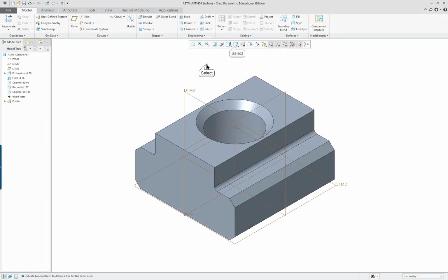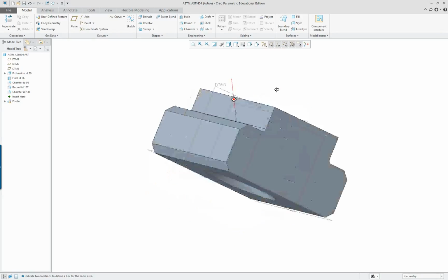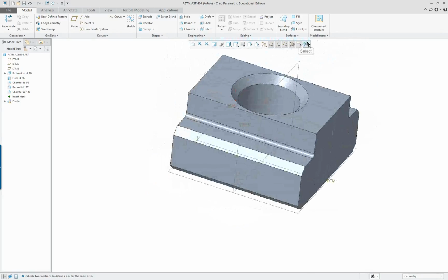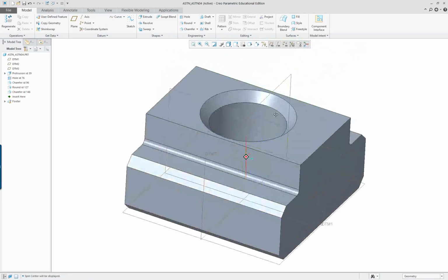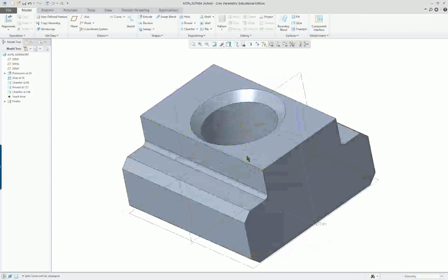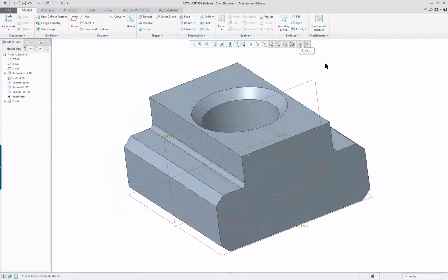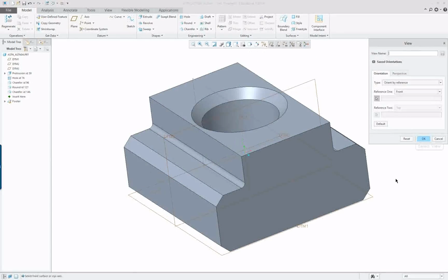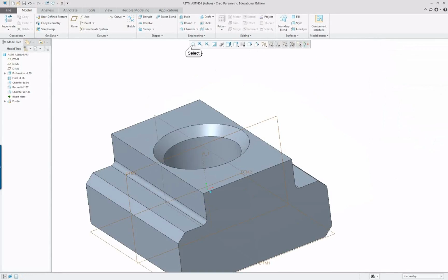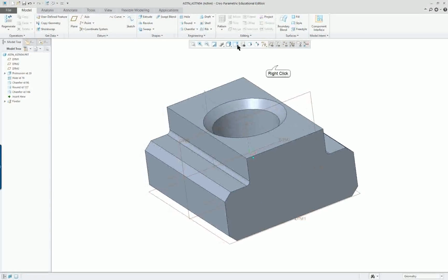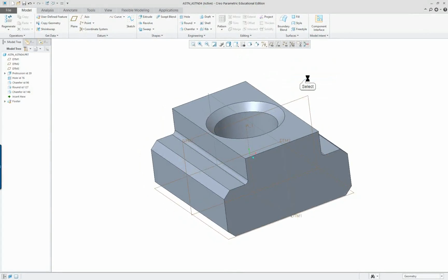And we talked about all these already. We've got our standard views. And in this case, we only have the selections here, standard orientation. Default orientation, you can actually reprogram this one to be anything you want. For instance, if we wanted to program it to be over here, I'm going to turn my spin center back on so it's easier to grab a point. It'll go right to the middle automatically rather than being at the position for rotating. So reorient, and we won't go into the reorient right now. We're just going to refit, and if we want to, either right mouse button, standard orientation.